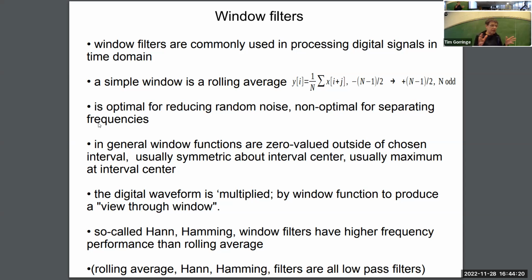So it's an example of basically when you apply a window, when you use a window filter, really the typical window is just some range of samples, say a range of n samples. Samples earlier than that are weighted by 0, so they're ignored. Samples later than that are weighted by 0, so they're also ignored. We only look at the n samples in that window.